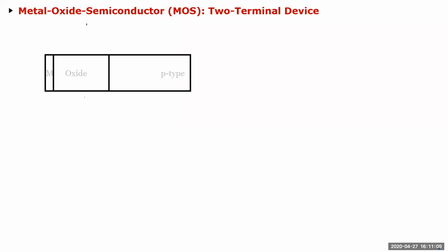So that's our goal. And in semiconductor, we usually deal with 3 types of material. When we said we can't do anything with metal, right? The metal Fermi level is embedded in the conduction band. Even though I put a high electric field, I will not be able to drive away the electrons. I can't make it non-resistive, so it is always conducting, right? So I can't use a metal. I can't use an insulator, because there is no charge inside it.